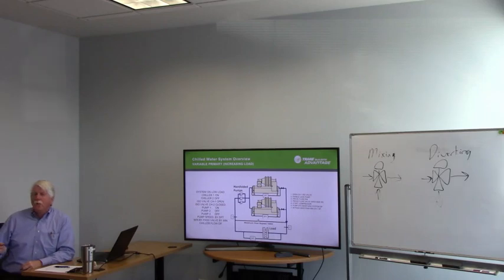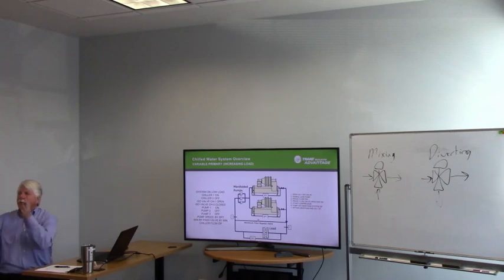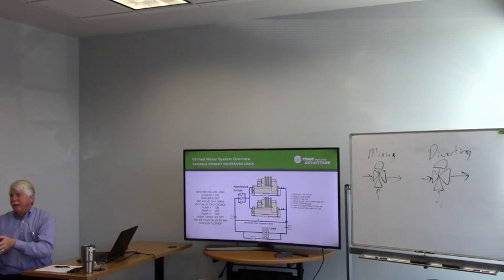But it's a vendor that Trane Company is using for their low flow protection on their chillers. Okay, so we used to use DPs and paddle switches. Both of those have issues with them. Neither one is good and neither one is bad. But what we do is we use the IFM on the machine. Now that's wired to the controller, so the machine can't start unless that's there.